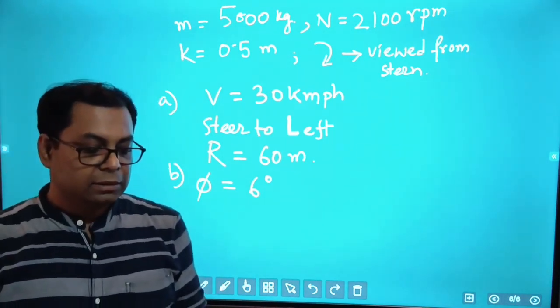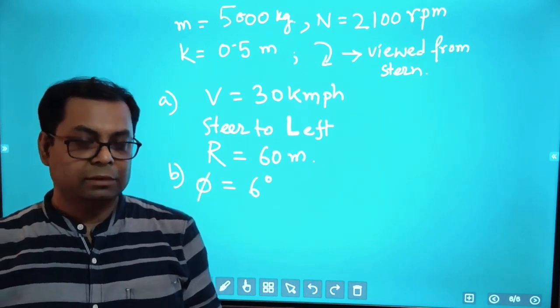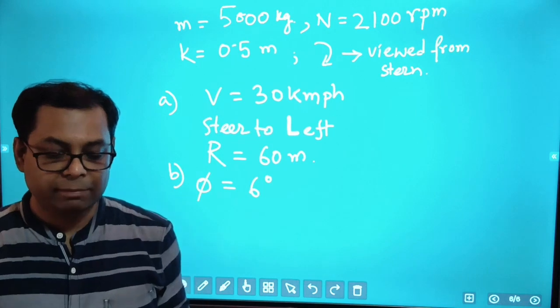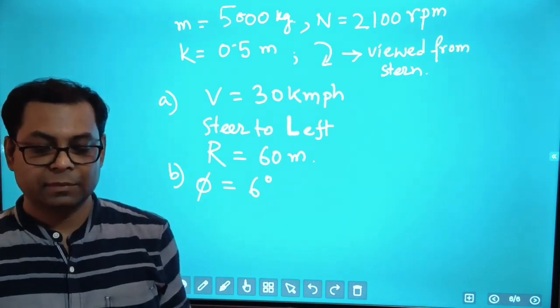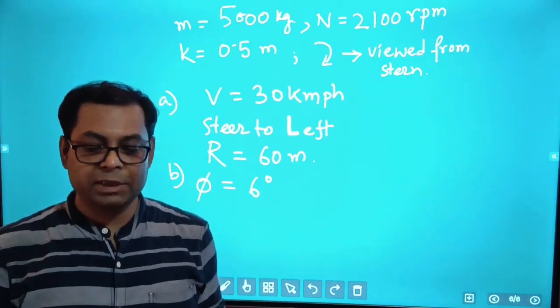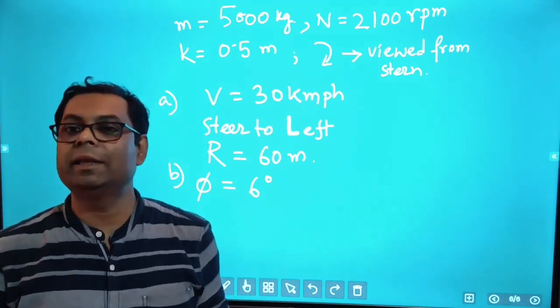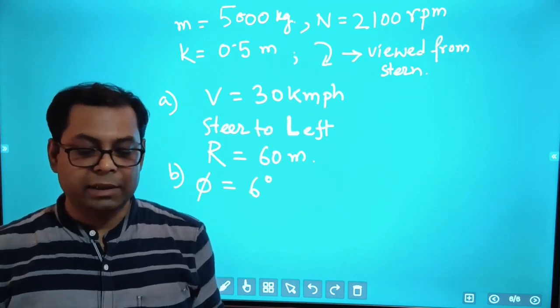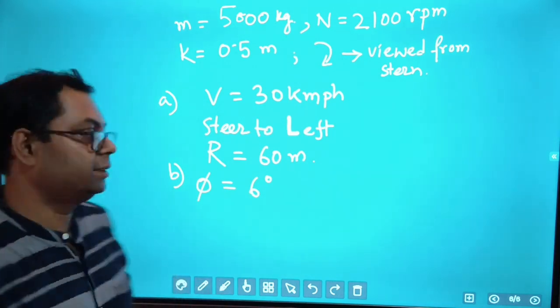The bow is falling with maximum velocity. The motion due to pitching is simple harmonic in nature, and the time period is 20 seconds.